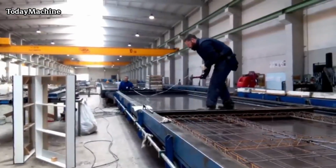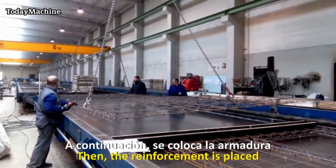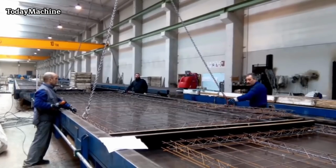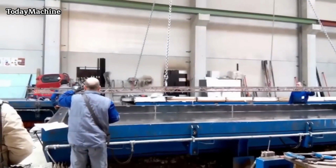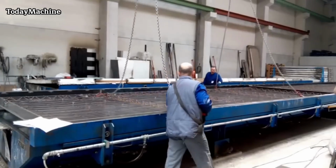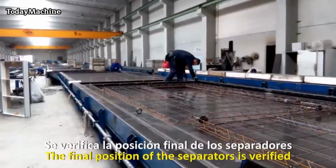Once the release agent has been applied and is ready, the next step involves positioning the separators on the table. Separators are devices or elements that are strategically placed on the table to define the shape and thickness of the precast panels. Proper placement of separators is essential to ensure that the panels meet the required specifications and dimensions. These separators act as molds or dividers that guide the concrete into the desired shape.